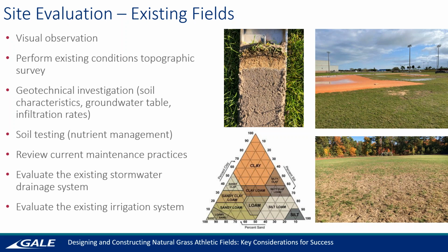Do you actually have under drains? Do you have catch basins in the corner? Are they silted up? Have they ever been cleaned out? Have the pipes been cambered? Things like that, right? If you're in an area that's subject to flashier, heavier and longer precipitation events, depending on where you are in the region, your area could tend to flood, and you want to be able to drain it and dry it out as quickly as possible so you can keep getting on there.